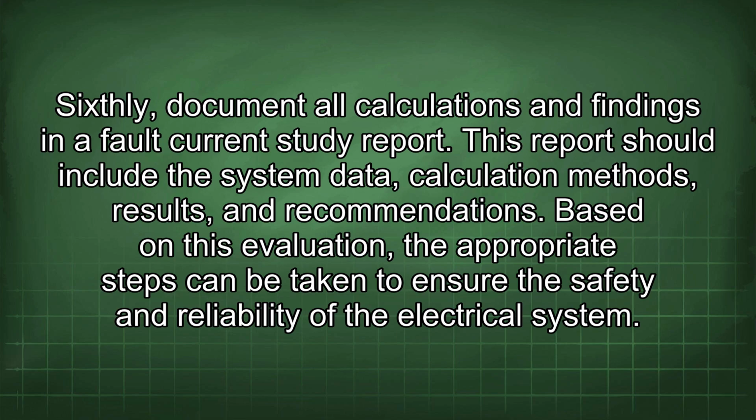Sixthly, document all calculations and findings in a fault current study report. This report should include the system data, calculation methods, results, and recommendations. Based on this evaluation, the appropriate steps can be taken to ensure the safety and reliability of the electrical system.